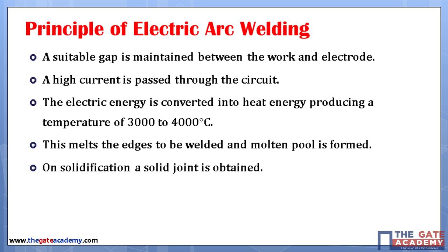A high current is passed through the circuit. The electric energy is converted into heat energy, producing a temperature of 3000 to 4000 degrees Celsius. This melts the edges to be welded and a molten pool is formed. On solidification, a solid joint is obtained.